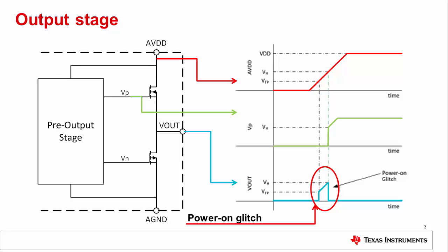You can also try adding a small resistor to ground in parallel with the load. This can allow the DAC to quickly dump some of the energy to ground, but has some undesirable side effects. Current consumption will increase, and the DAC output voltage may droop during normal operation.